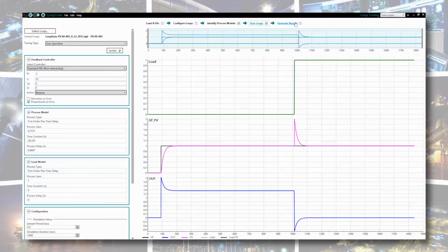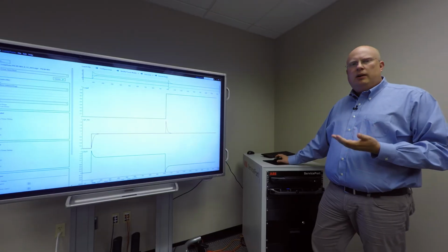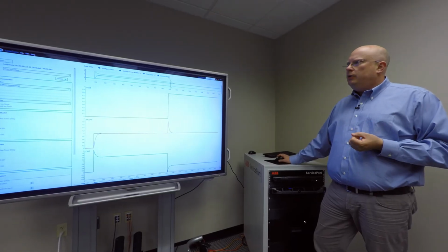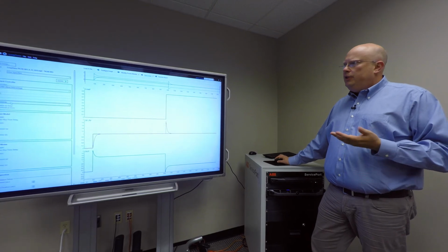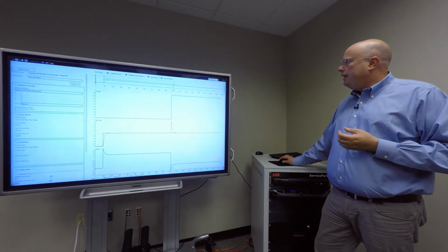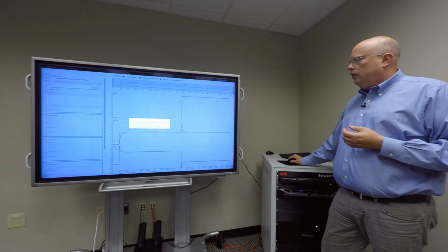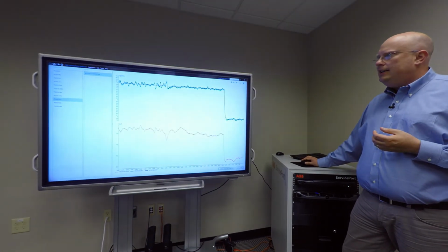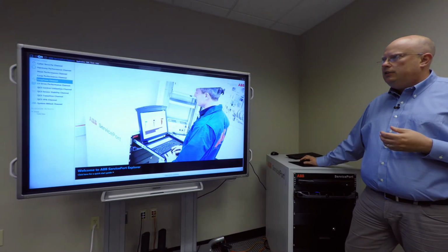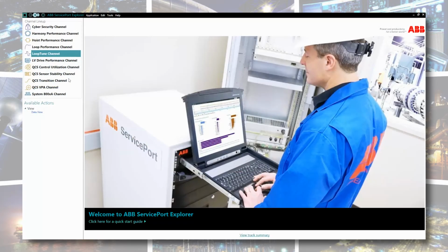I can generate a report as well to have a support. What did I do? What did I select? What was the result? It's a really powerful way of keeping track of what's been done. So after I put these values in, I can go back to my channel, and the next time we collect data, I will actually see how this change I did affected things, because the loop performance channel will keep measuring that.